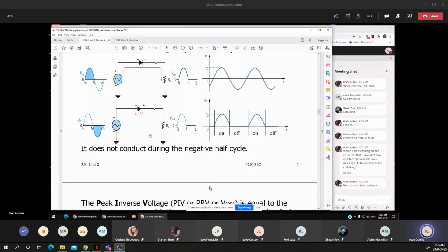And the current, you notice, is zero, meaning the diode will act as an open switch, or in the off state. If there is no current, what is the voltage across the resistance? Ohm's law, isn't it? It is 0 multiplied by the value of RL, meaning the V out, or the output voltage, is 0.